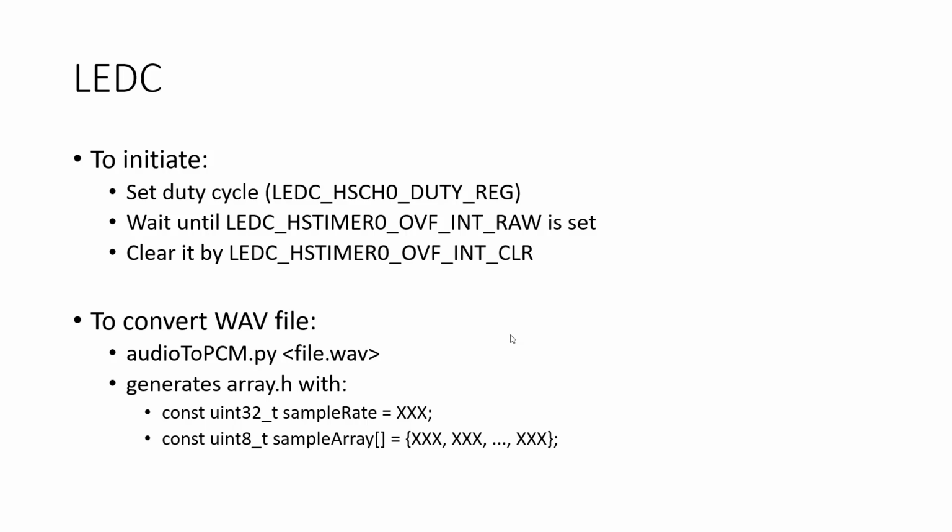How much memory do we have to work with? Like how much time in a song does that actually end up being? Well, it depends on the sample rate. We can make the sample rate garbage. You can still hear Megalovania out of it. But yeah, we have 1 megabyte of flash to work with. That comes out, for like a 16 kilohertz sample rate, to like 30, 45 seconds.